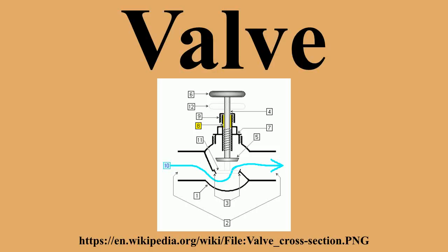Plastic bodies are used for relatively low pressures and temperatures. PVC, PP, PVDF and glass-reinforced nylon are common plastics used for valve bodies. Bonnet. A bonnet acts as a cover on the valve body. It is commonly semi-permanently screwed into the valve body or bolted onto it.